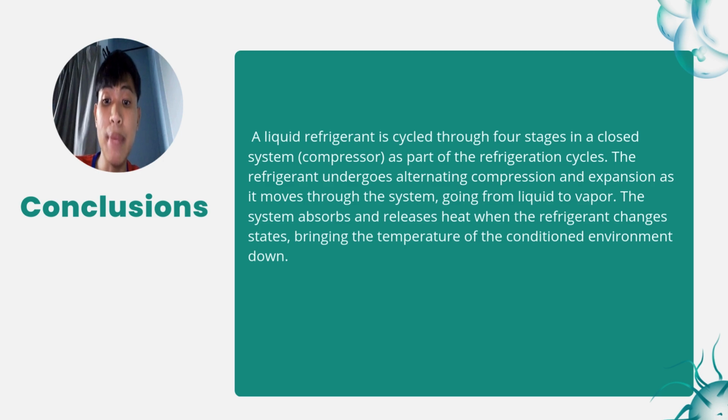What is COP? As mentioned by my roommate, Afina, in the previous slide, COP is calculated as the ratio of heat absorbed by the refrigerant in the evaporator, the cooling effect, to the work input from the compressor. It serves as a measure of the refrigeration system efficiency. So how can we get the COP, the desired result over the required input? We can conclude that for COP, we want to find the cooling effect and also the work done on the system.